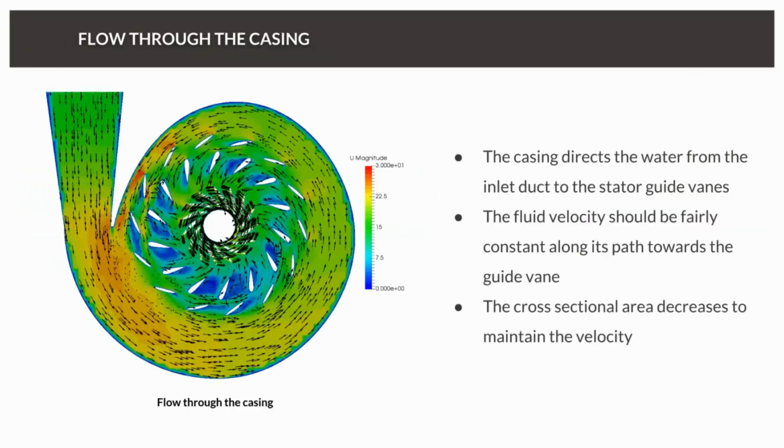Taking a look at a slice through the top, here we're showing velocity, and the cut plane that you can see is shaded by velocity. So the blue is basically zero velocity, and that's pretty much where we've got recirculation and potential cavitation, and then up to the red, basically where we've got the highest velocities. And the goal really is to have all of this area coming all the way around the outside, to at least have the same volume flow rate.